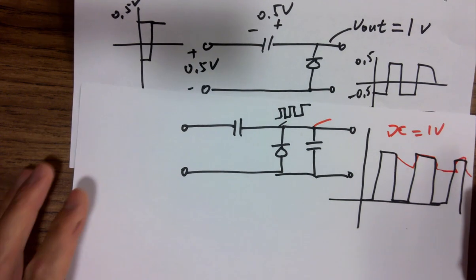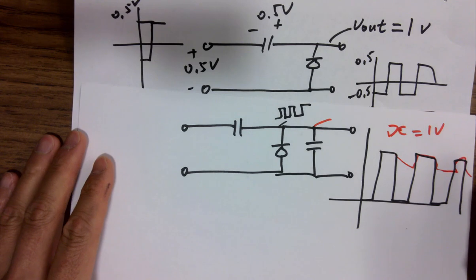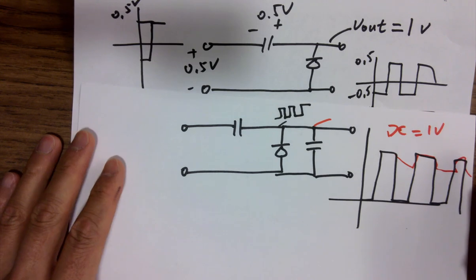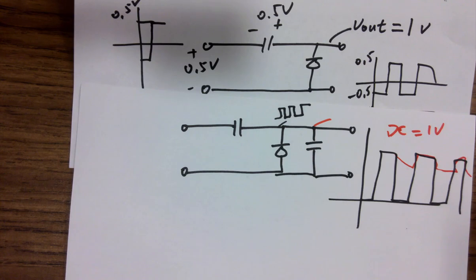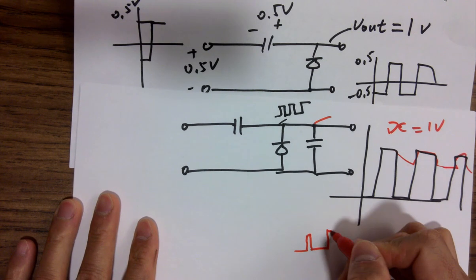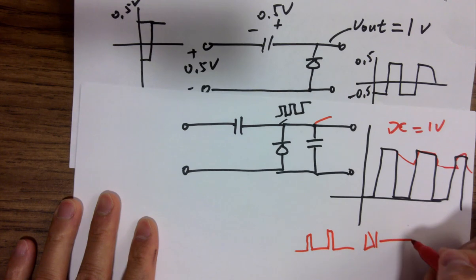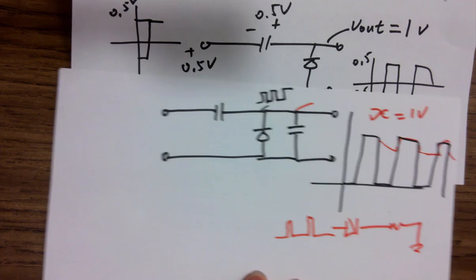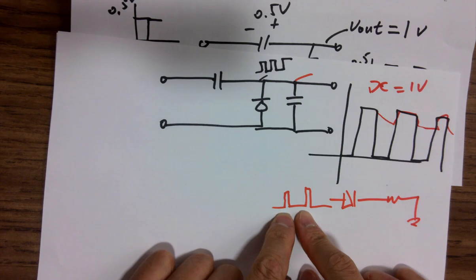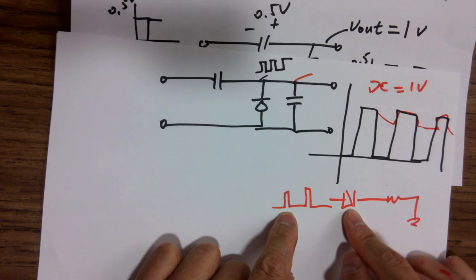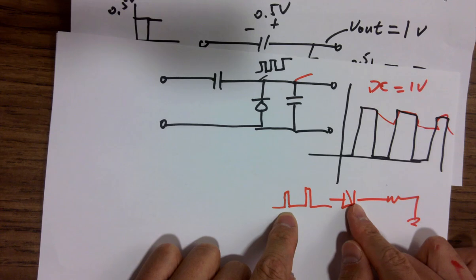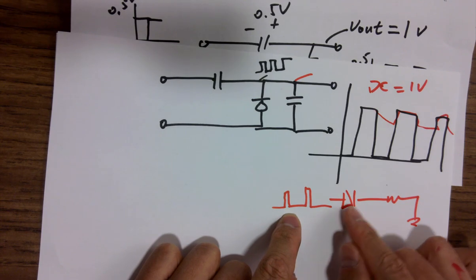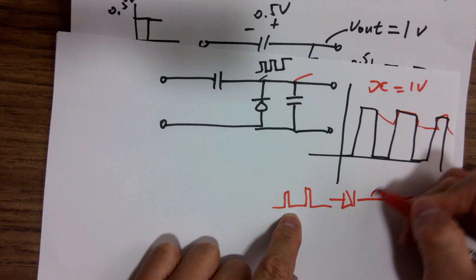So is this how they convert pulse width modulation into an actual voltage, like going from that pulse to an actual straight voltage value? No. But similar. That's a very good question. When you connect the pulse width modulation to an LED, it is pretty fast, a lot of times in kilohertz frequency, and you couldn't even see it blinking. Sometimes you can probe this output to see what that looks like.